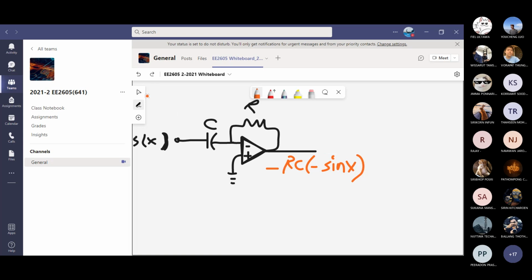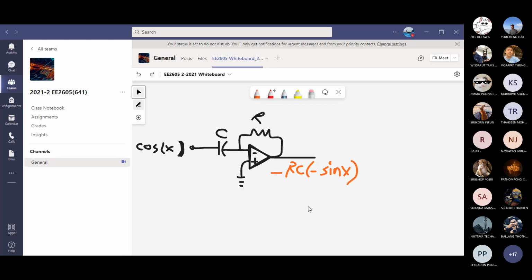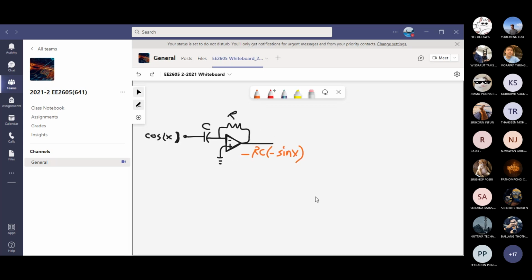It will become minus. You want a minus sign? This is fine, but you want a plus sign at the end. This is not okay. Let me draw a summing op-amp. This is the last stage. Minus, plus. And then this is the final output voltage, V out.